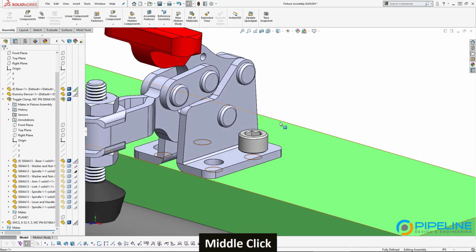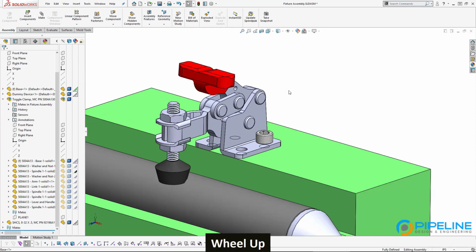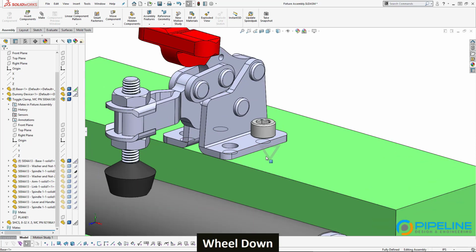So we can do like we did with the coasters and create a copy and then mate it to all of the different holes, or we could use a pattern. A really nice thing about using the Hole Wizard is now I can tell the assembly to copy this screw for every hole we've drilled. As long as all these holes were done under the same feature, the Hole Wizard, we did the Hole Wizard once and I made 4 holes, I can use that information and just tell SolidWorks to put as many screws in there as there are holes. So here's what we're going to do.